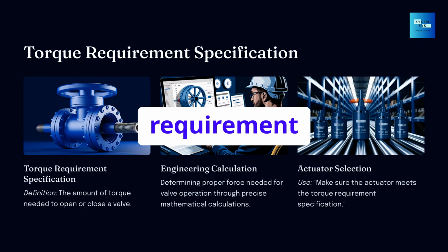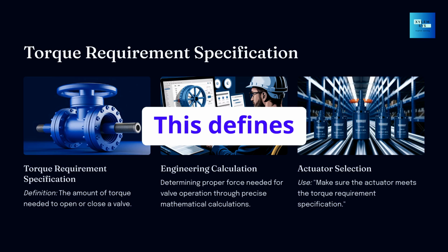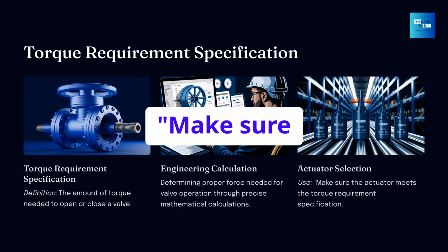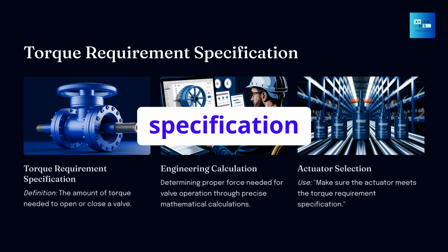15. Torque requirement specification. This defines how much torque is needed to operate the valve under pressure. Ensuring correct torque helps prevent stem damage or failure. Make sure the actuator meets the torque requirement specification before starting the installation.